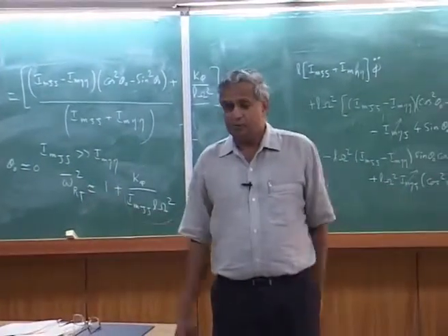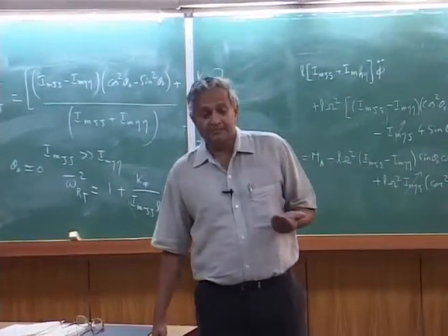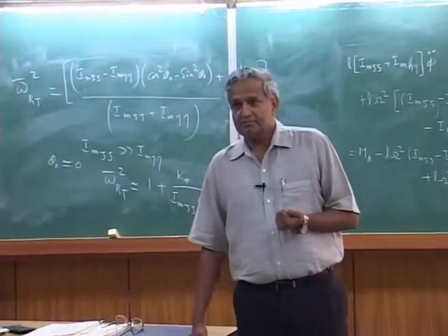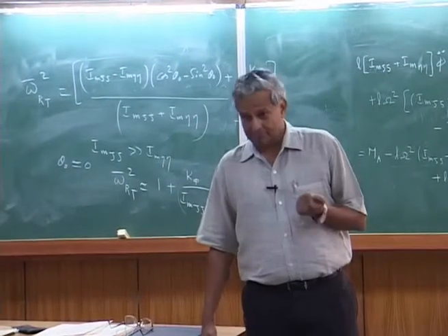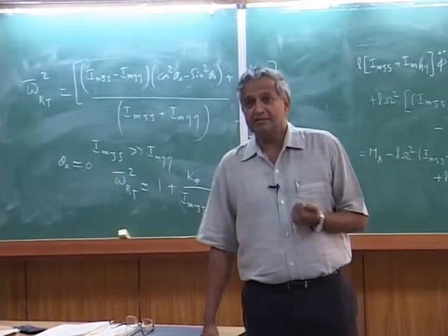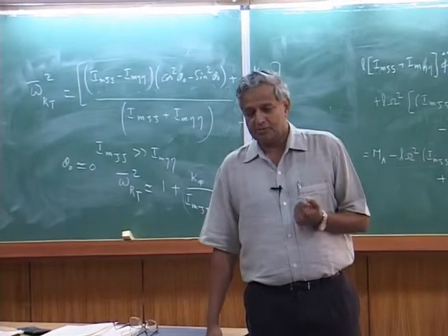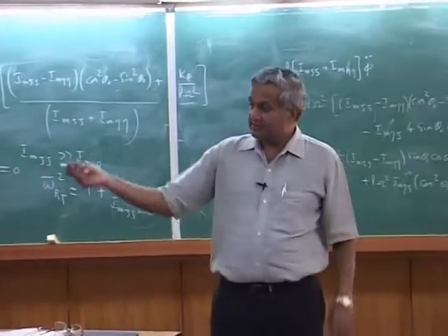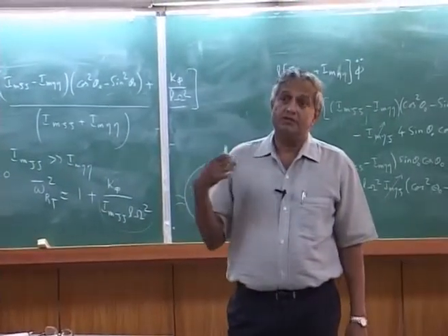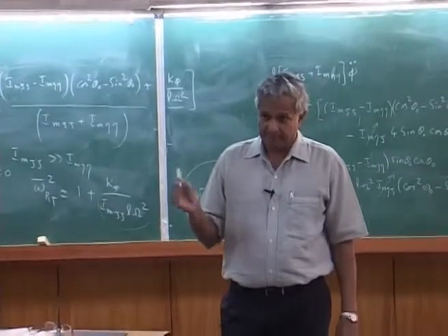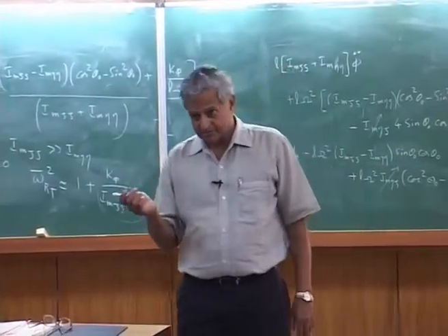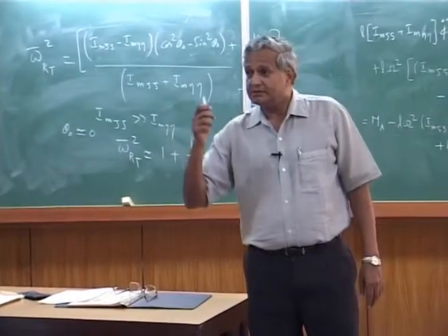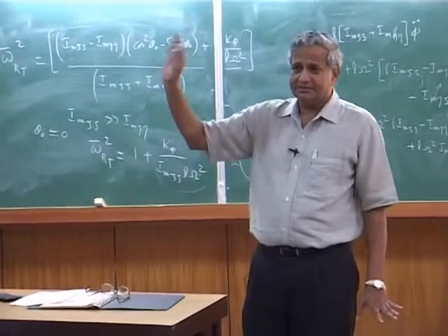That's it. Why is it valid? The reason is axial stiffness, EA, is always much higher than bending and torsional stiffness. Therefore, it's all right. Then in the bending problem, you have an axial, because it's combined, if you want to treat axial motion, centrifugal force you have to bring into effect. If you make it a rigid blade, it is taken care of because you are not bothered about that.